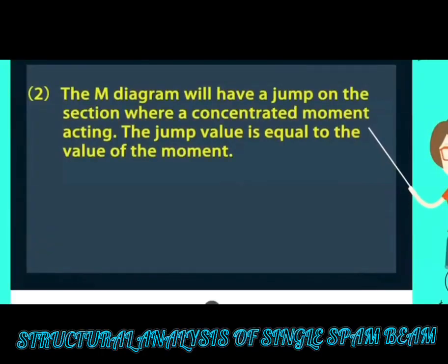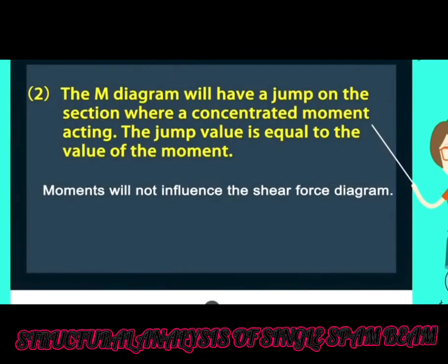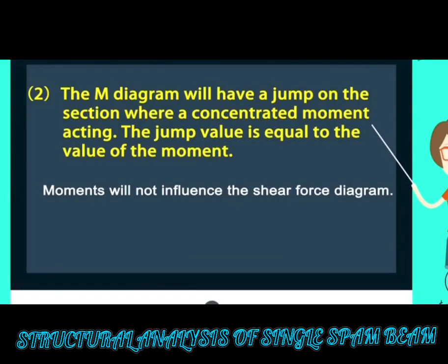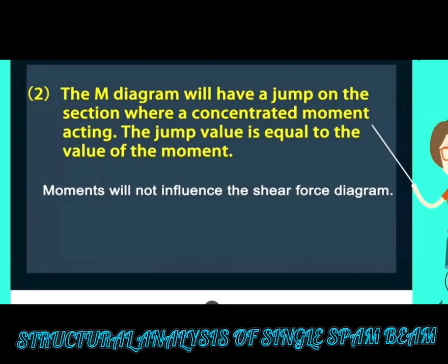The bending moment diagram will have a jump at the section where a concentrated moment acts. The jump value is equal to the value of the moment. Moments will not influence the shear force diagram.